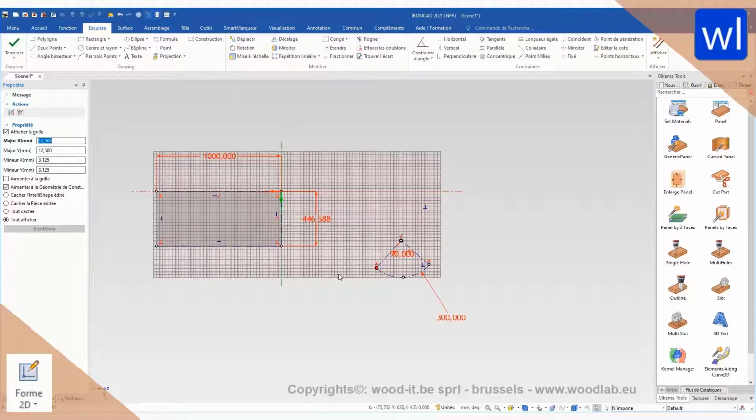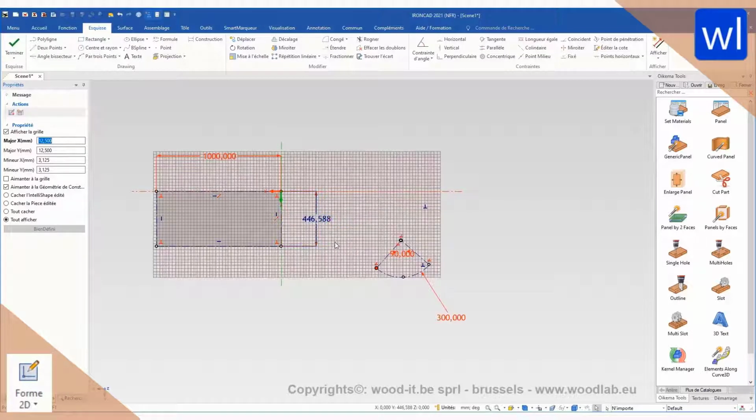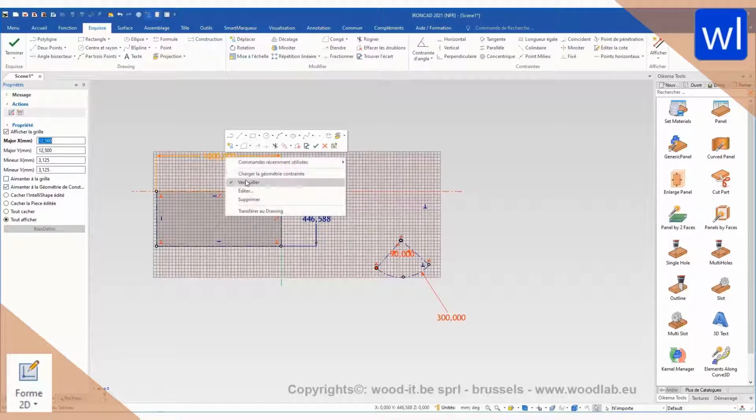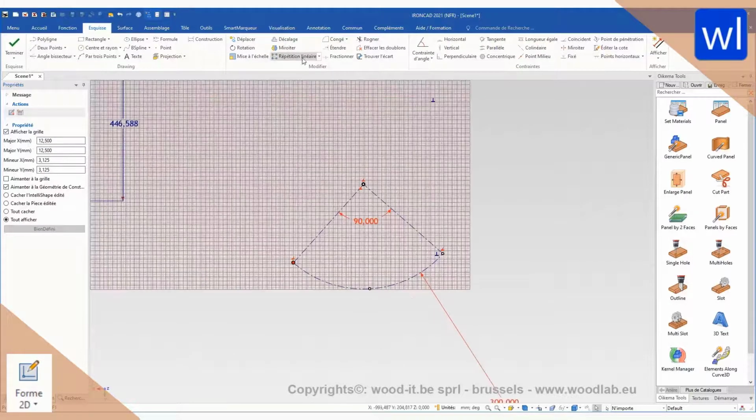The rectangle on the left represents the rectangular dimensions of the panel required for your curved part. Understand that in the end your curved part will be inscribed in this rectangle. The dimensions of the rectangle will therefore be defined by the angle and the radius of the part. It will therefore be necessary to unlock the smart dimensions of the rectangle. To do this, select the smart dimensions, right-click, unlock. They will take on the color blue and will therefore be there for informational purposes.